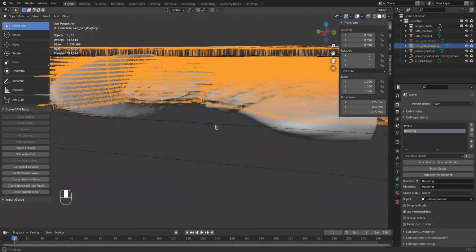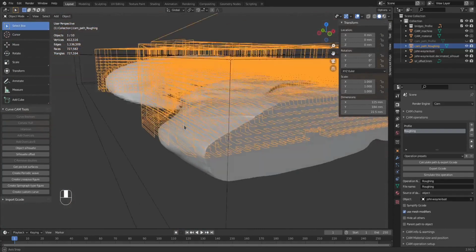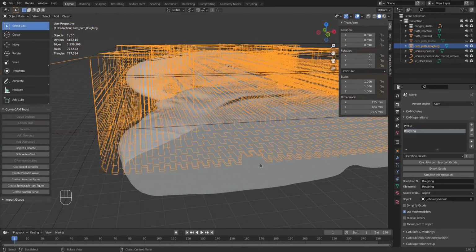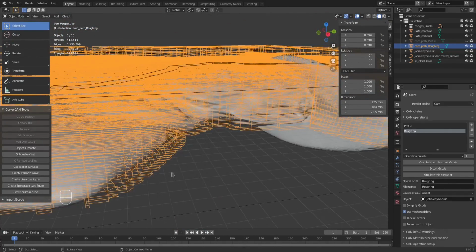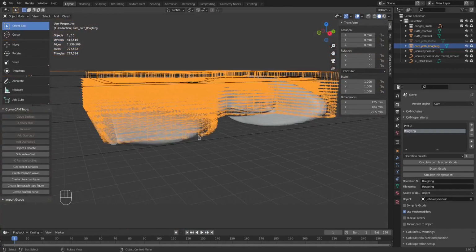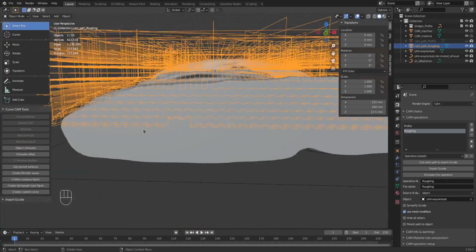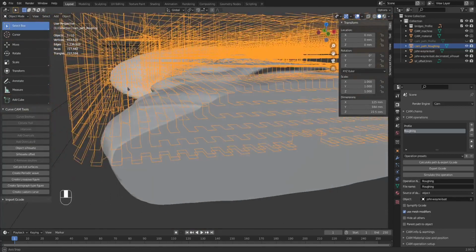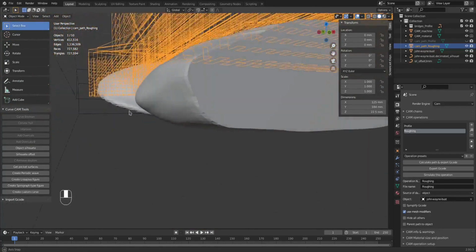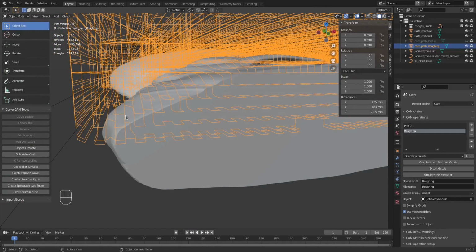That is the toolpath for my roughing operation. It came out well. It looks like it minded the bridges there. Everything's alright, yeah, it skips the bridges. It leaves about a 0.5 millimeter of skin. You can kind of tell. It's hard to see, but I can see that it's leaving that little 0.5 millimeter of skin for the finishing pass to come back and handle.